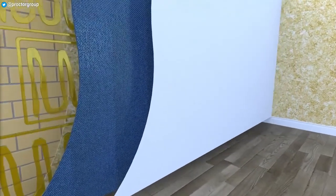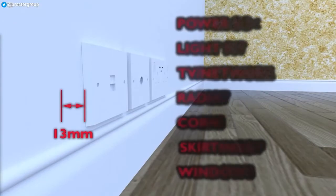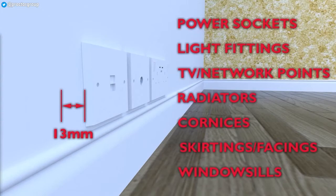Once installed, the system provides a significant reduction in heat loss, with a minimal 13mm increase in wall thickness, meaning in most cases, sockets, switches and TV network points can be left in situ and features such as cornices and window sills can be left as is, with no modification required.